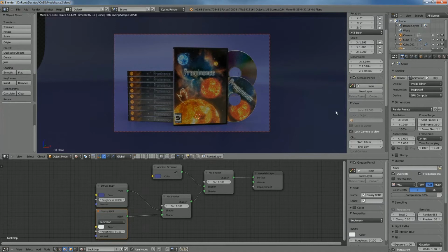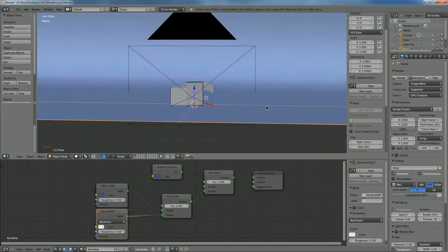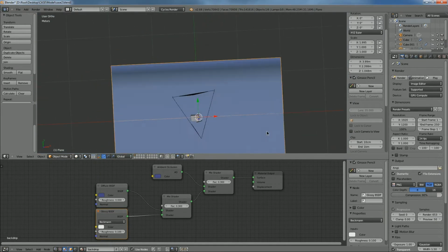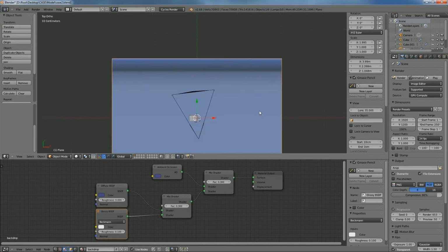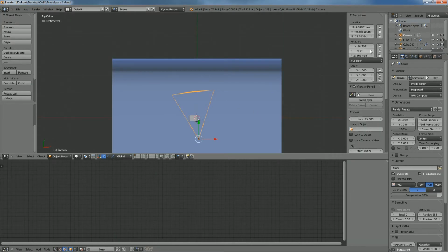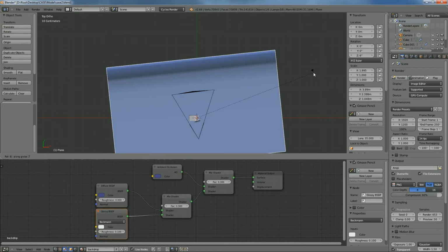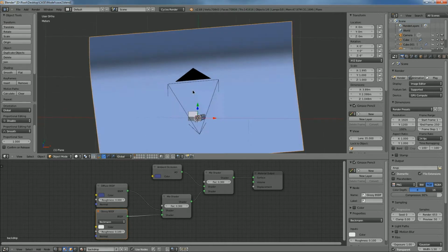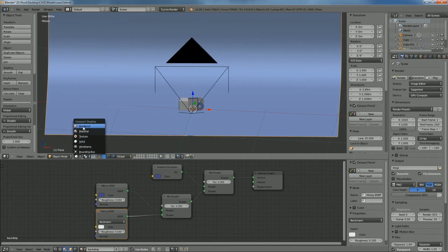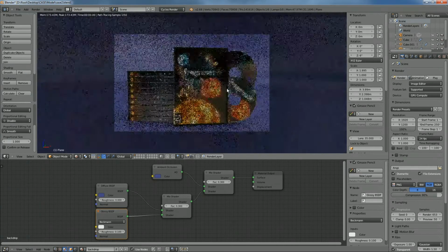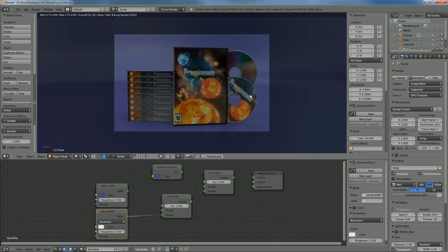Okay, so I'll just come over here, and we're just gonna rotate this cyclorama here to be in line with the camera. So you can see here that we've rotated it -6 degrees, I guess, on the z-axis. So we'll just rotate it, or I guess 6 degrees on the z-axis. So let's type in 6z. And yeah, it's more or less parallel. And let's go back and look at how that looks now. Okay, yeah, that's a bit better.